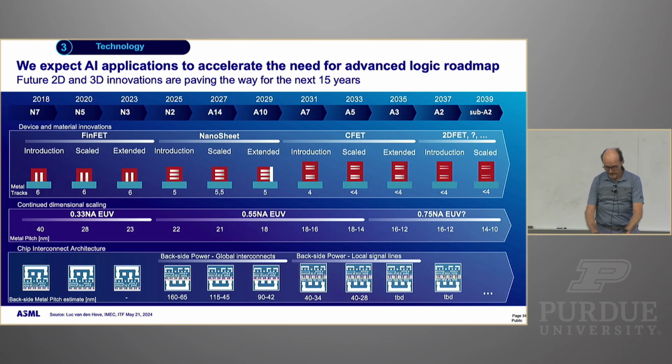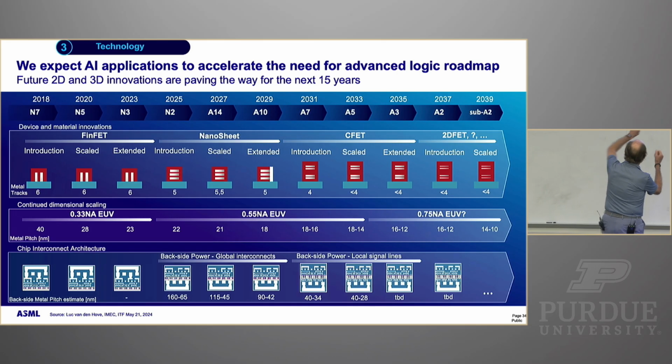But if I put a little insulator here, a gate oxide, and a gate on top of it, the potential on this gate can attract some electrons, and then these electrons can start moving. So now I have conductivity. That was called a planar MOSFET, and we've had that for a long time. On this chart, that's further off to the left, further in the past.